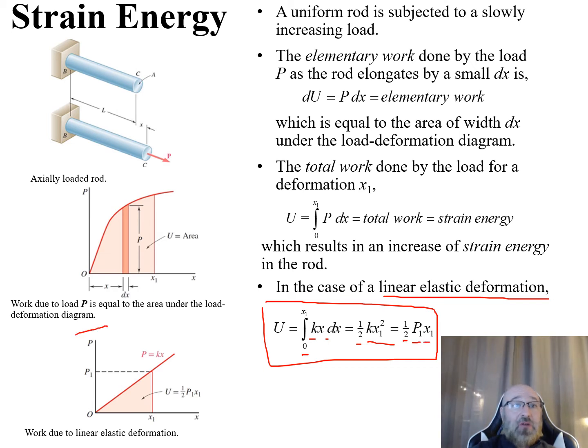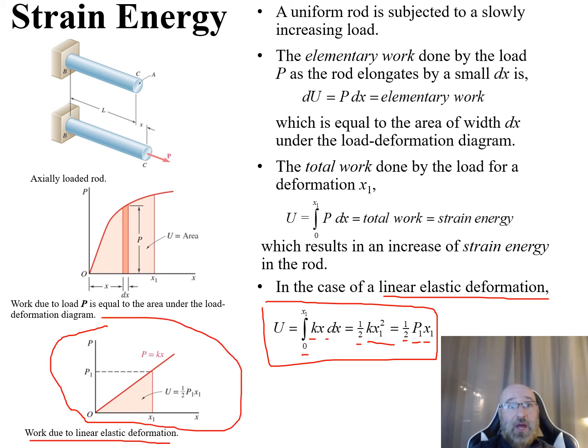So then we can come down to our diagram here for work due to linear elastic deformation. And we can see this, our U is the area under the curve from 0 to x1, just as we see in our integral, because our integral is going to be the area under a curve. And this goes up to our distance right here, P1, where we end this. So then we can see there is that equation that U is equal to 1/2 P1 x1.